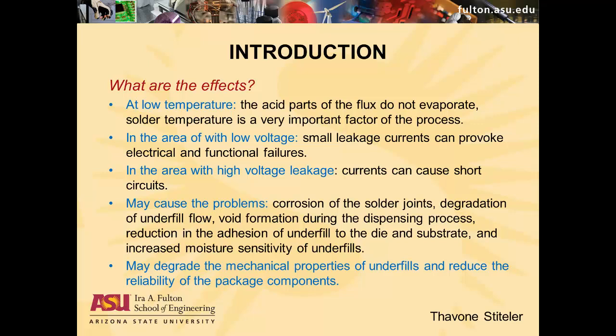Flux residue may cause problems such as corrosion of the solder joints, degradation of underfill flow, void formation during the dispensing process, reduction in the adhesion of underfills to the die and substrates, and increased moisture sensitivity of underfills. It may alter the mechanical properties of underfills and the bumps. These may reduce the reliability of the package components. Now I will hand it over to Jasmin.